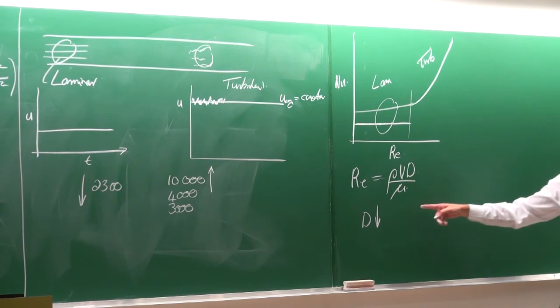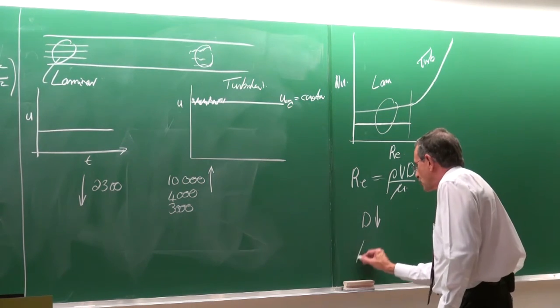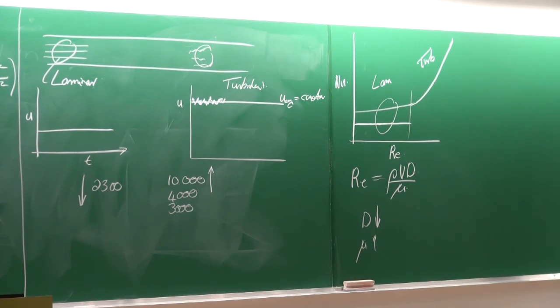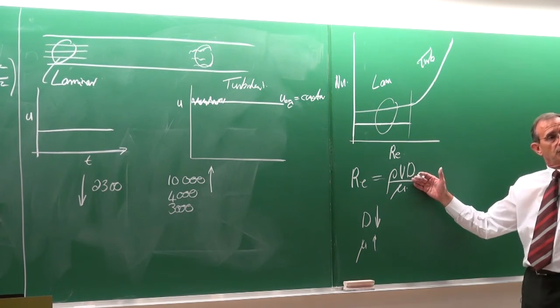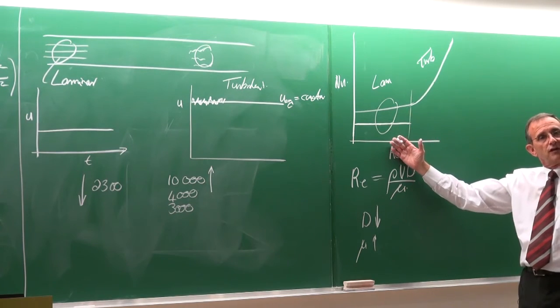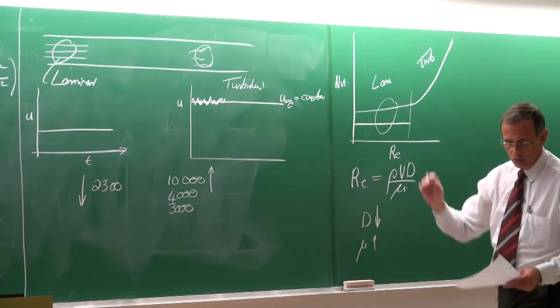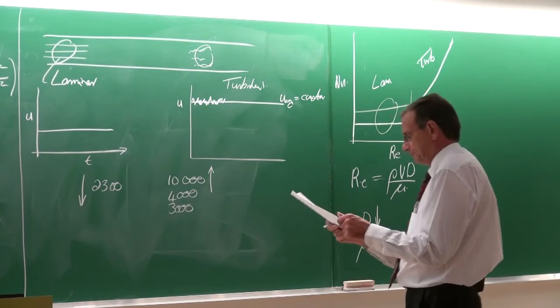So that is the first case, and the other case is when the viscosity becomes very high. So fluids with high viscosities, oils, glycols in a chiller is another very good application. In those cases, the Reynolds number can move into the transitional flow regime, or close to the transitional flow regime, or into the laminar flow regime.